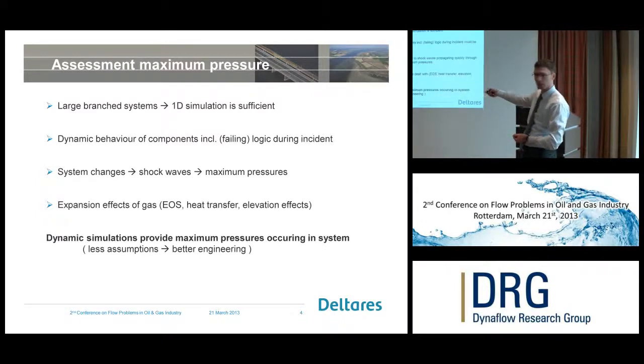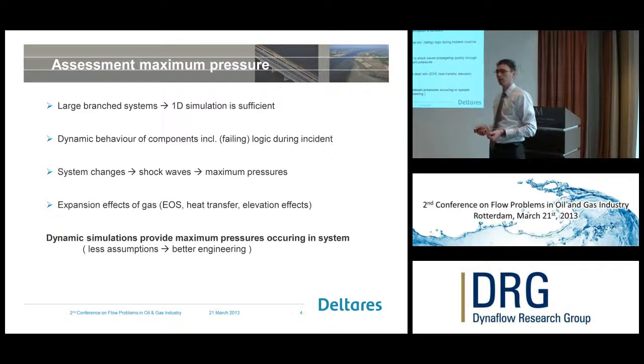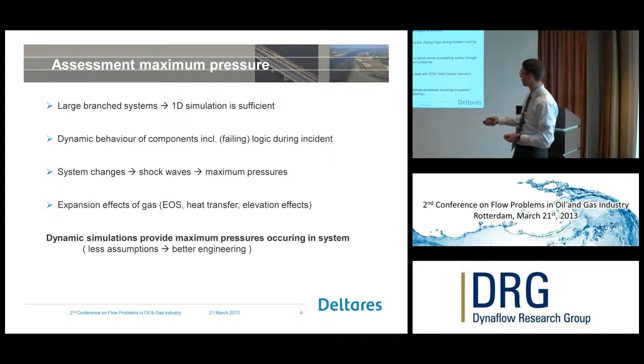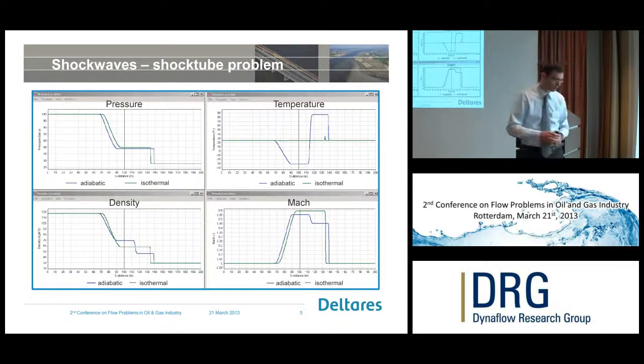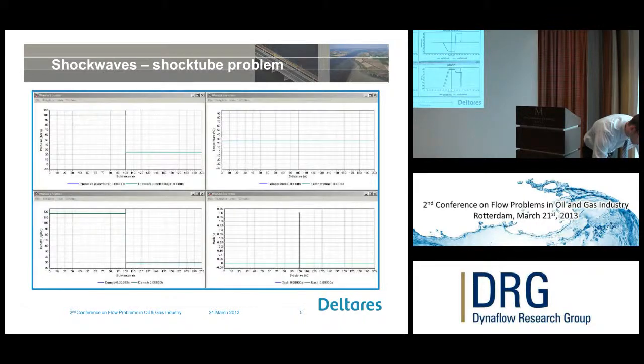I mentioned shock waves here, and that's typically what we see in the projects that we do. And a typical problem is that you've got a reservoir connected to natural gas, and during the startup phase your choke valve breaks open. So all the gas is just standing still, and then you want to start your operation, but your choke valve does not open to the maximum controlled normal operating CV, but it just breaks open. Now, to see what a shock wave then actually does, I've got a video here.